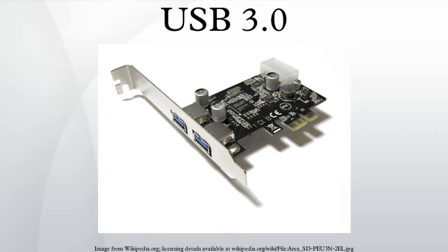The larger dimension for a USB 3.0 Type B receptacle is intended to allow connecting of either the larger USB 3.0 Type B plug or the smaller USB 2.0 or earlier Type B plug into a newer USB 3.0 Type B receptacle. Accordingly, a USB 3.0 Type B receptacle on a peripheral device can be connected using the corresponding plug end of a USB 2.0 Type B cable.